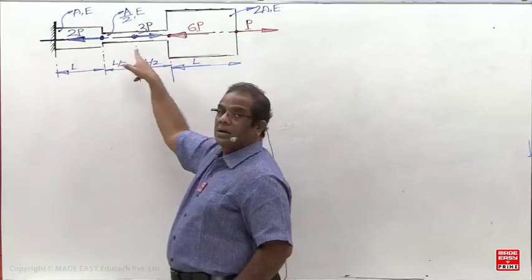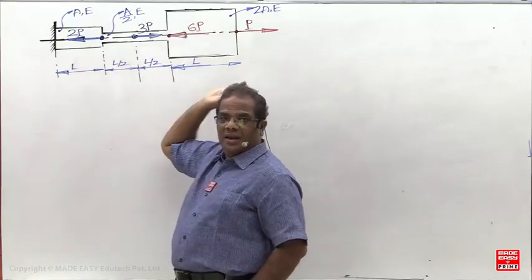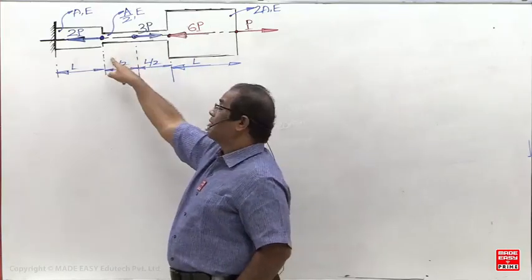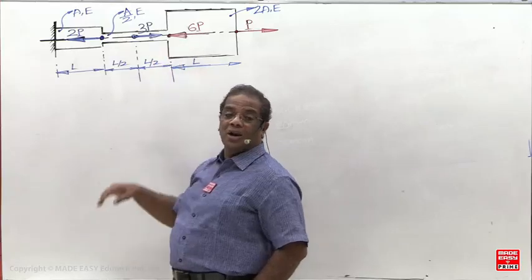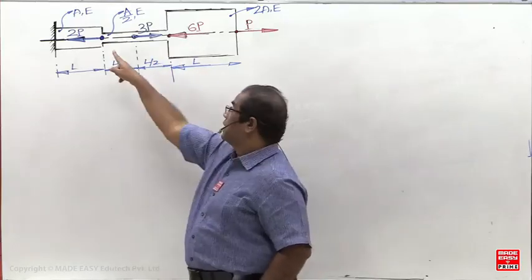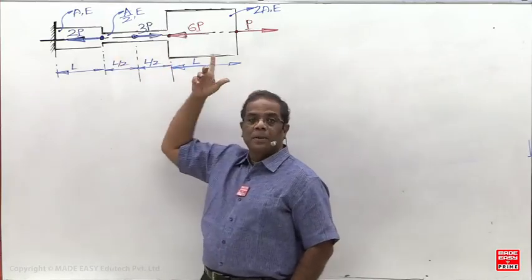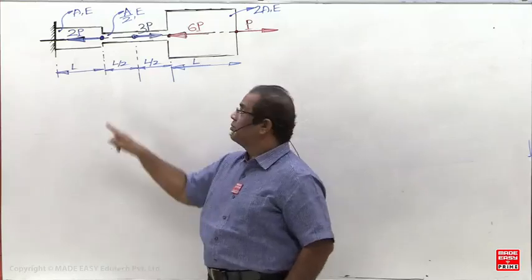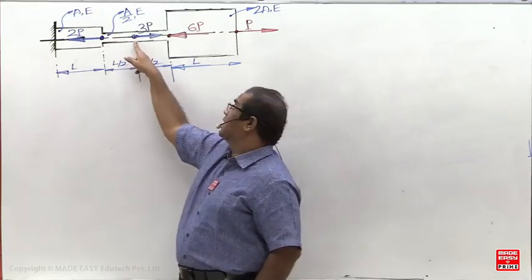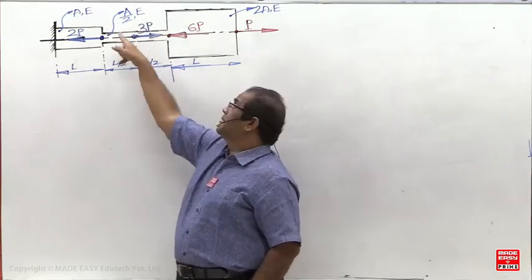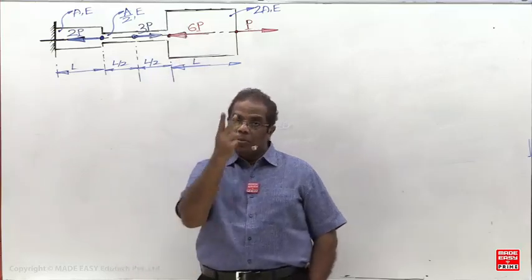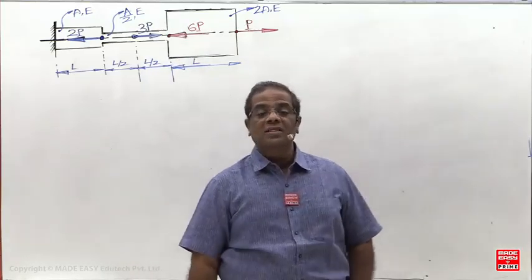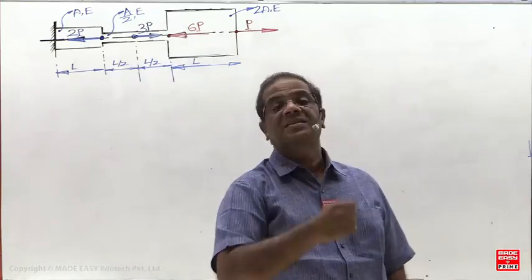Here to here is a single bar, with a single diameter. But here to here, the pure axial load condition is not satisfied. Here to here, prismatic is satisfied, but pure axial load is not satisfied. But here to here, pure axial load is satisfied. So how many bars should this be taken as? 2 bars. So overall this should be considered as 4 bars in series.